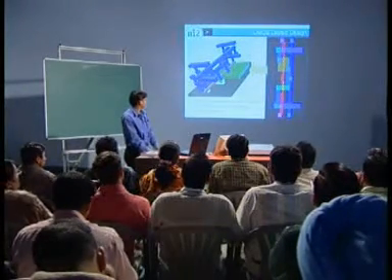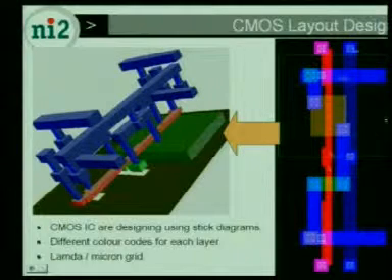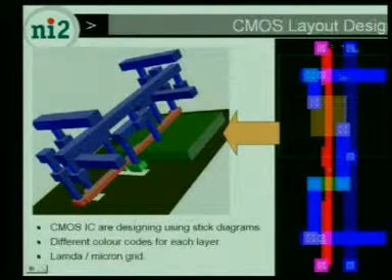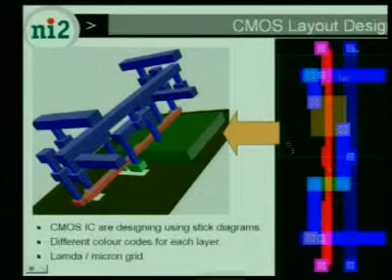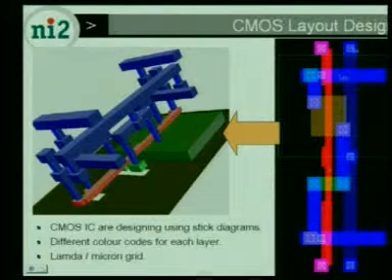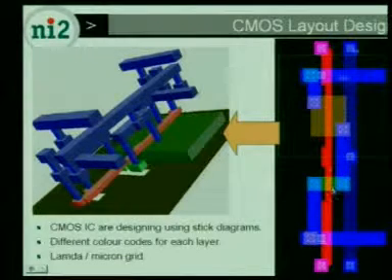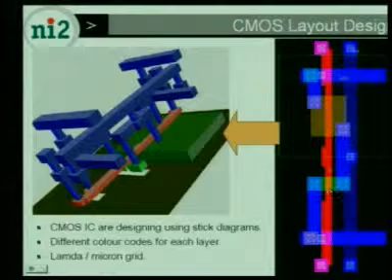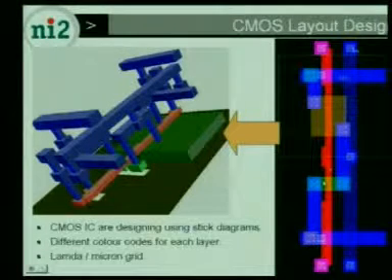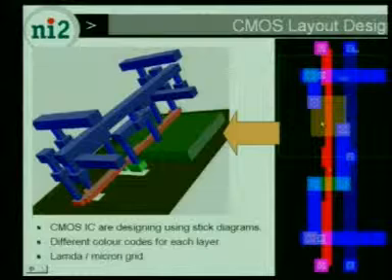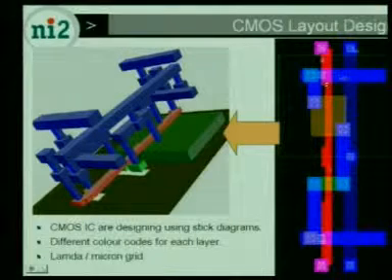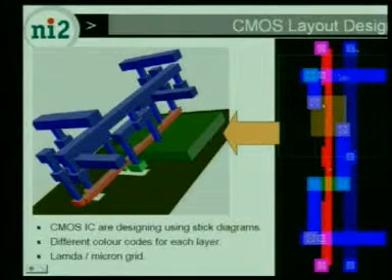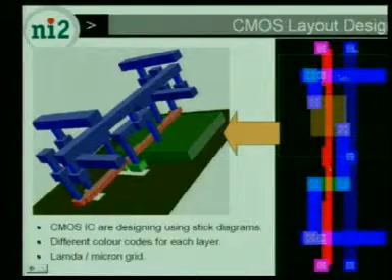What we will do, I will explain this by using the software. This black screen is by default P type, and this layout is for P, and this is for N. This red one is the polysilicon, and this green one is the diffusion layer for N type, and this is for P type. So, using the software I will create some masks for this PMOS and NMOS, and after that I will connect this gate. This will be the common